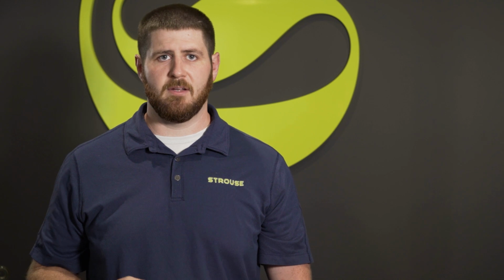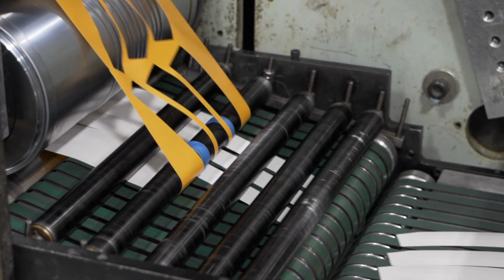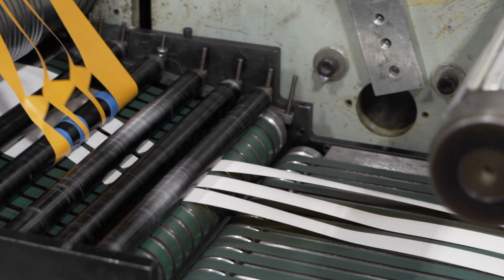When determining a looser versus tighter tolerance, your application really is what drives it. That being said, there are functional tolerances, and that is the key. You want a happy medium. You don't want something that's super tight and not manufacturable, but you don't want something that's super loose and is going to fail within your application. Having a super tight tolerance when it's unneeded is going to have negative drawbacks later down the line as you're sourcing your converted part goods, and when you're having stack ups of other parts which are sourced throughout the process as well.